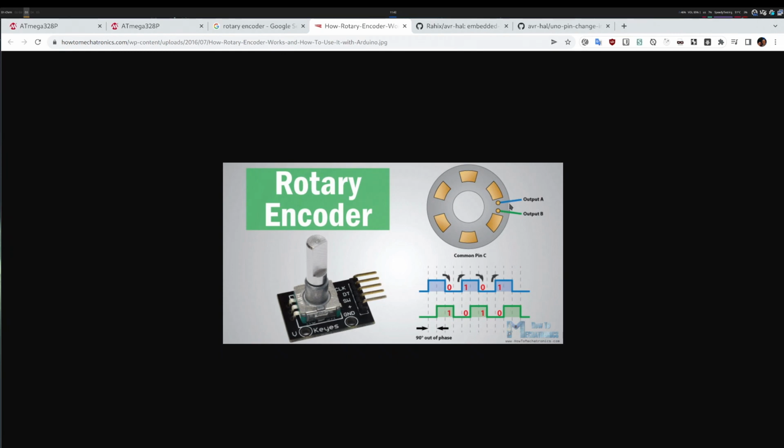So inside the program, what I have to do is check when my clock changes, either it goes high or it goes low. And then if the two values of the pins are the same, this means I turned towards the left. And if they are different, like in this diagram, this means that I turned towards the right. So I know when I turn by watching the clock. The clock changes, this means something got turned. And then I can see the direction of the turn by comparing the clock and data line. If they are the same, it's one direction. If they are different, it's another direction.